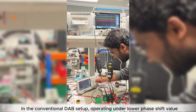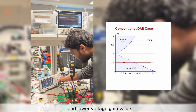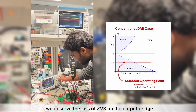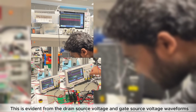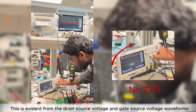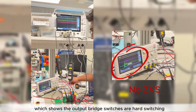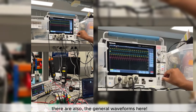In the conventional DAB setup operating under lower phase shift value and lower voltage gain value, we observe the loss of ZVS on the output bridge. This is evident from the drain source voltage and gate source voltage waveforms, which show the output bridge switches are hard switching. There are also general waveforms here.